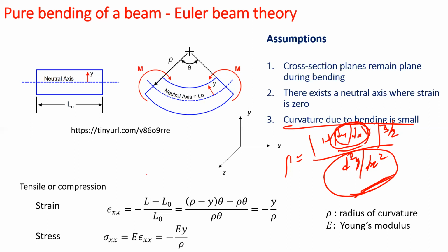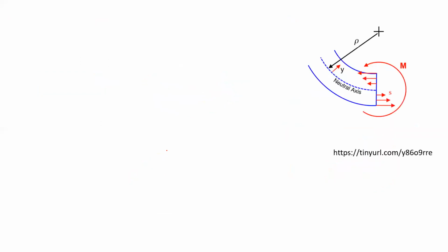So you cannot take a wire which is sitting next to your computer. It could be the wire of your mouse or the headphone. You can't say that you will use Euler-Bernoulli beam bending theory, although the structure is still slender. In fact, it is more slender than most of the engineering structures that we consider, with a slenderness ratio much higher. So this is again a key issue, that the curvatures do not always have to be small; it is an assumption that needs to be relaxed. So this was one more limitation of the strength of materials course.